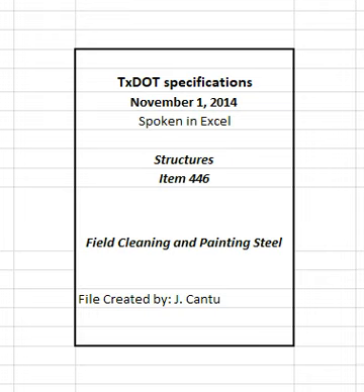Feather edges of sound paint around cleaned areas. Ensure all surfaces to be painted are completely free of oil, grease, moisture, dirt, sand, overspray, welding contamination, slag or acid residue, loose or flaking mill scale, rust or paint, weld spatter, and any other conditions that will prevent the paint from forming a continuous, uniform, tightly adhering film.